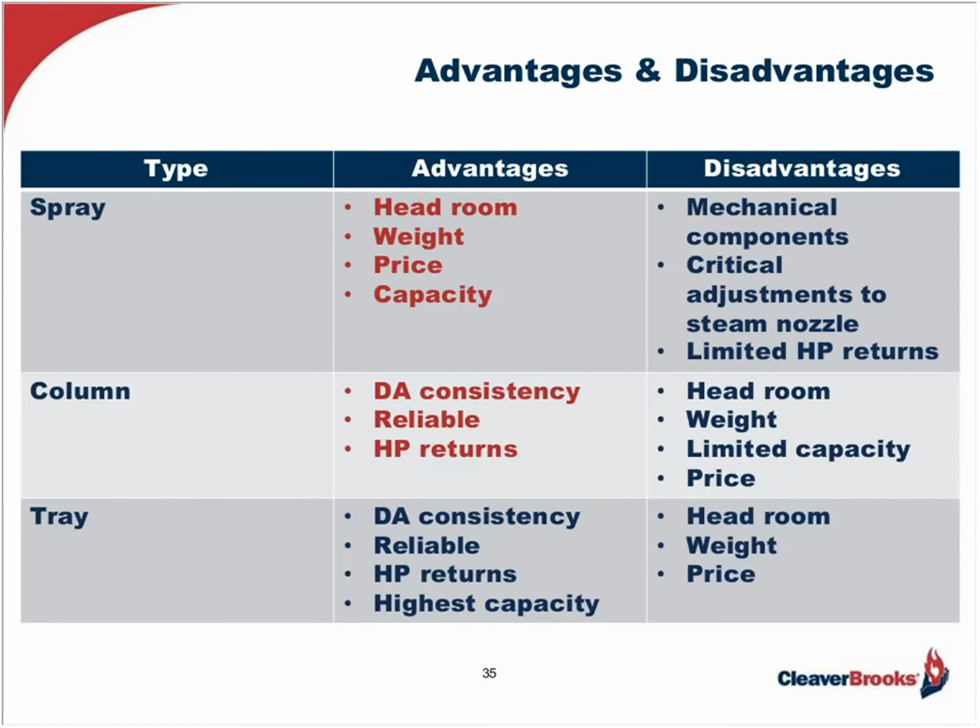And this is because the spray deaerator has a couple of moving parts, which may require more mechanical maintenance in the field over the life of the equipment, thereby affecting routine operating cost and reliability. Now, more specifically, the spray deaerator utilizes two stages of deaeration. In the spray head area, about 90% of the deaeration is accomplished, and then the other 10% is done in the scrubbing or spring-loaded nozzle area. And because of these moving parts and associated dynamics, misalignments can occur, affecting the reliable and consistent deaerating process.